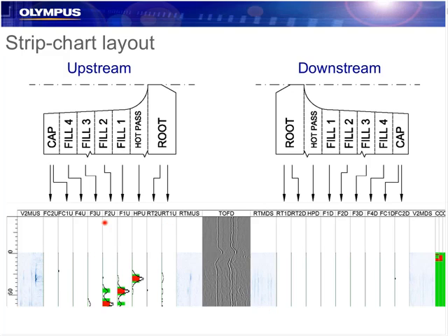Typically these zones are focusing mainly on the bevels for lack of fusion. We want to make sure we don't miss any internal defects as well. And then we also have coupling channels. We want to make sure that the probes are adequately coupled all the way through the scan, so there are no coupling problems affecting transmission of sound and therefore detection of defects. So we'll look at this a little bit bigger, but just kind of trying to lay out the general process at this point.